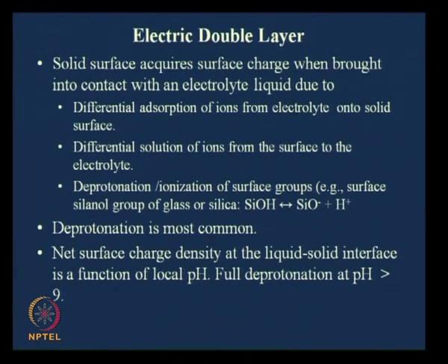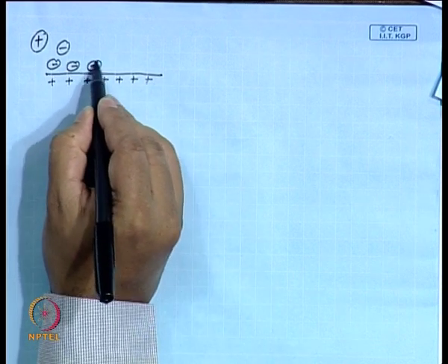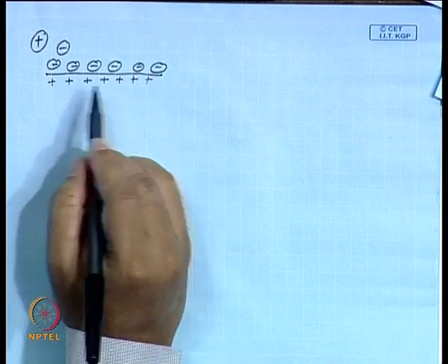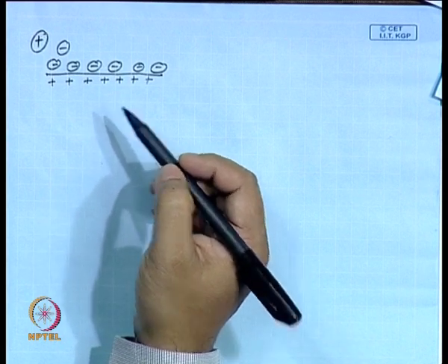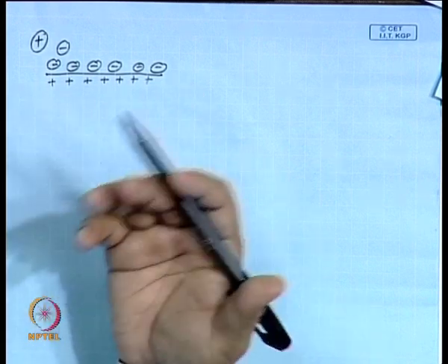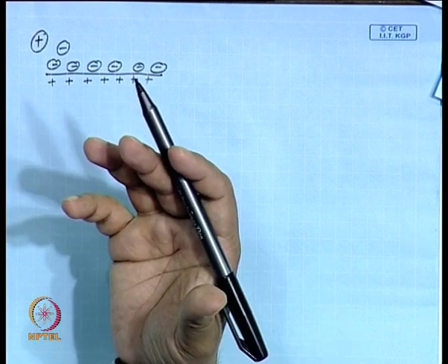If you have a surface, you will develop some charge there, and because of this charge, the opposite charge from the electrolyte will be attracted to the wall. So, if you have all plus here, you will have all minus sitting here, like this. This happens with any wall material. If you have a pipe, this is happening too, but at a macro scale you probably do not care much, because it is insignificant. But at a micro scale, in a micro channel, these phenomena can be important. Because of the scale of the problem, these phenomena need to be studied.